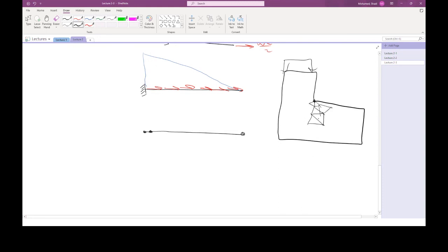So you can solve the problem with larger triangles away from the stress concentration, whereas close to that, you have very small elements. I mean, imagine instead of using one small element here, use small elements everywhere. It's exactly like using many small elements in here. You are going to get a curve that is much closer to this.